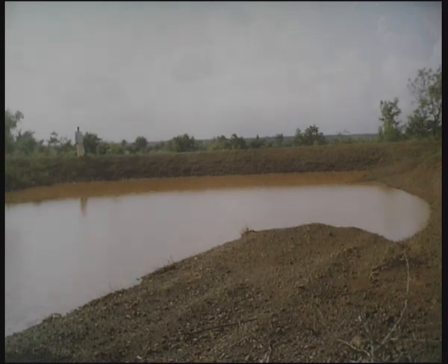And again, the surplus course may pose problems of erosion and things like that. So therefore, such earthen check dams will have to be limited to the small tributaries of the main stream and should not be attempted on the main stream where the flood discharge is going to be quite significant.